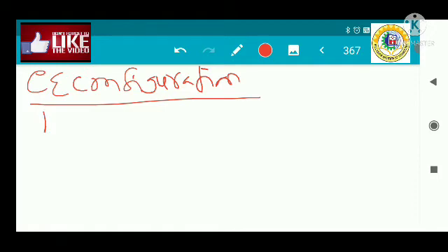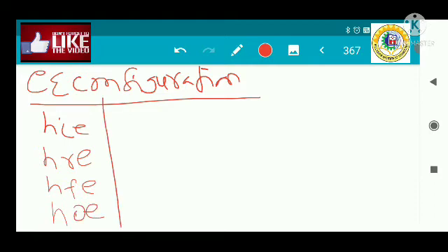there is a parameter HI, so in the case of the common emitter it is replaced by HIE. There is a parameter HR, that will be replaced by HRE. There is a parameter HF, that will be replaced by HFE. There is a parameter HO that will be replaced by HOE. So in the case of the common emitter, the H parameter is written by this.